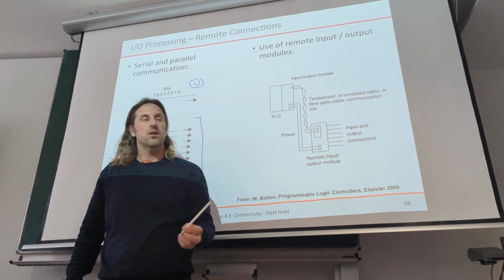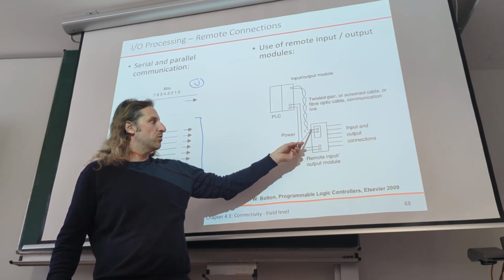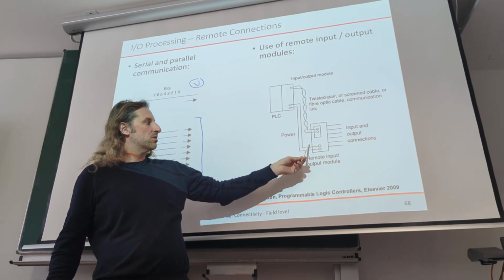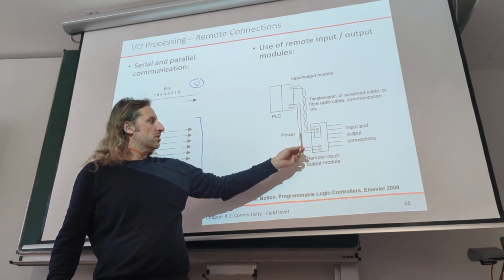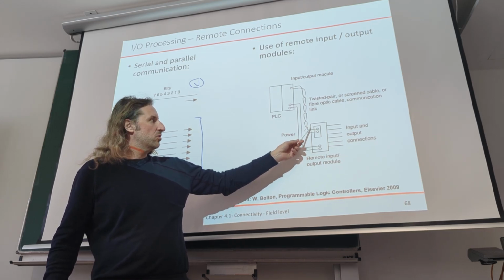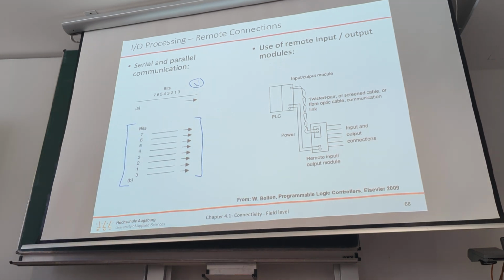So in the end we would need 3 cables at least, but usually we have 4, or 2 and 1 optic cable. The reason why we actually use 2 twisted pair connections typically is that we use a differential signal.